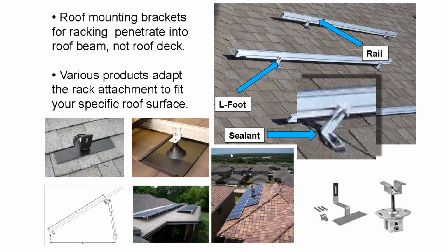First off, there's racking components for almost every roof surface. When I got into the industry, there was not an integrated flashed standoff. The old-fashioned way would be to lag screw into the roof and goop the heck out of it. It's not a very good practice. Now we get these really awesome flashed standoffs that slide underneath the shingle, and the lag screw goes through it, but the actual hole is up underneath.